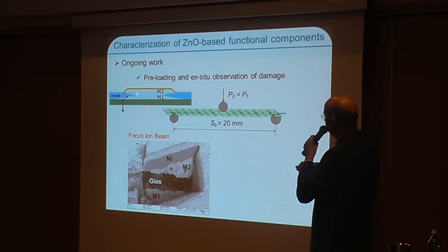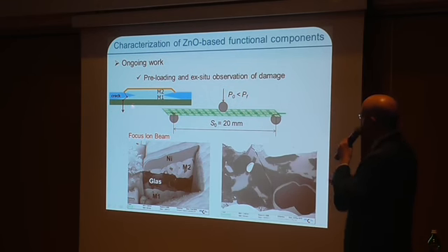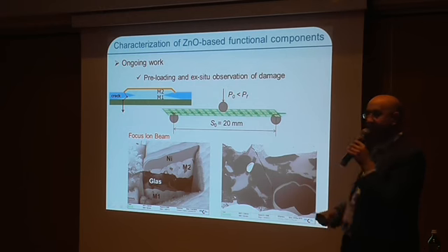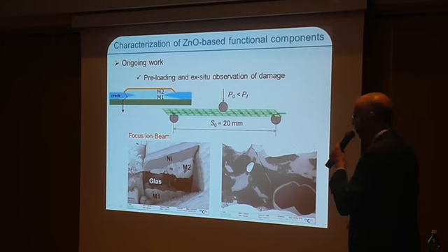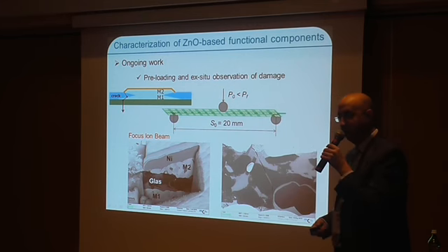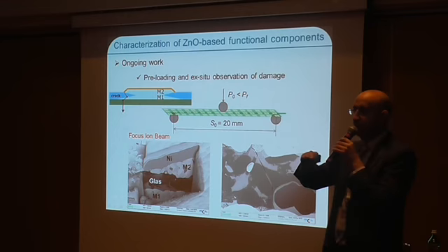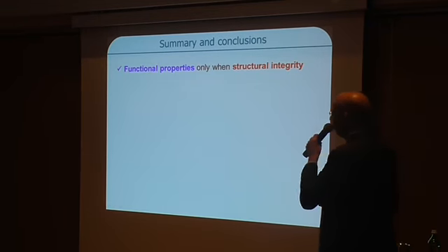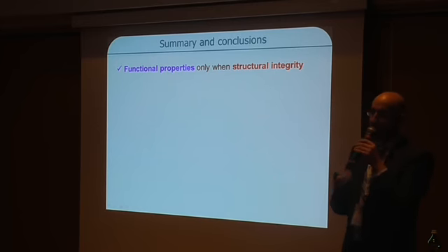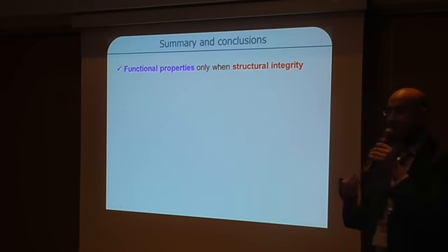you look inside, you can identify here this nickel is the yellow layer, then you have metallization, glass, and so on. And if you look closer, we could see for this particular configuration how a crack originating due to residual stresses of the system could propagate, but it will stop in the metallization underneath. Whereas for the other configuration it will cause catastrophic failure. And that could explain the results that otherwise could be very difficult to understand if you don't have this